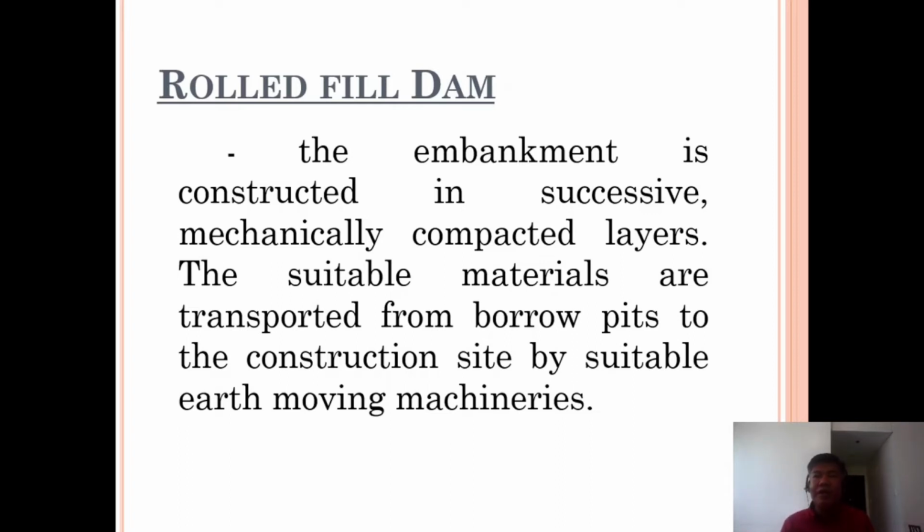With the rolled fill, you lay the materials layer by layer, then compact, and the suitable materials are transported from borrow pits. The most important thing to consider in an earth dam is that the material should be located near the structure, because there is a cost incurred in transportation, hauling, and so on. So you always have to consider that.